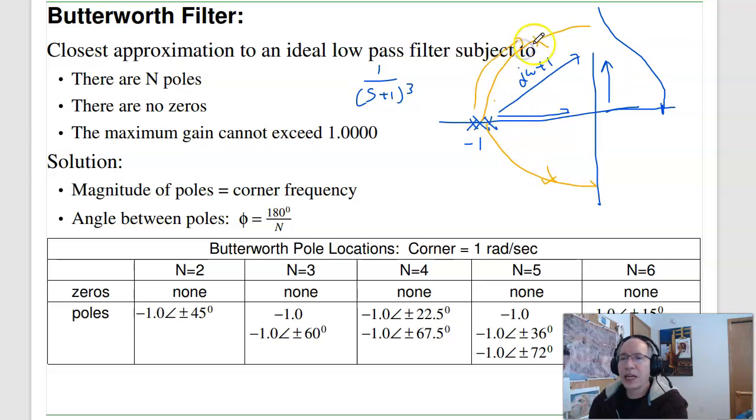What's going to happen is I now have a resonance at s equals 0, close to this pole. I now have a second resonance. So the gain goes down, and I have a second resonance. Then the gain drops off. And likewise, complex conjugate. As I move the angle of this pole, the gain at these points starts to increase.